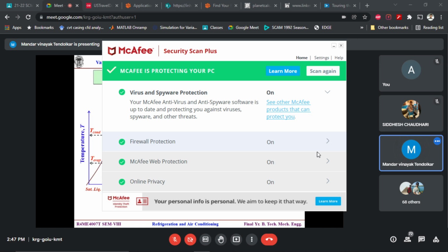Correct? Now you consider the Carnot cycle. So over here I get the area as E, then 2 double dash, then 3, then C, and then E. Agree? A simple rectangle. Yes. Now what about the vapor compression cycle? It would be E, then 2, then 2 dash, 3, right?